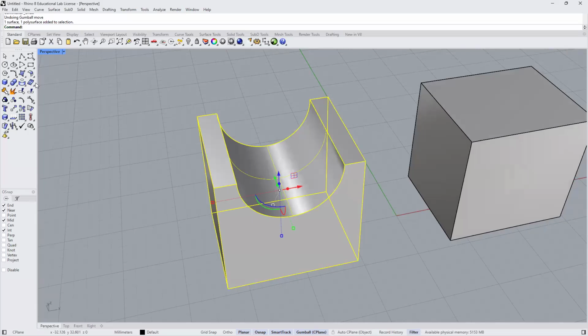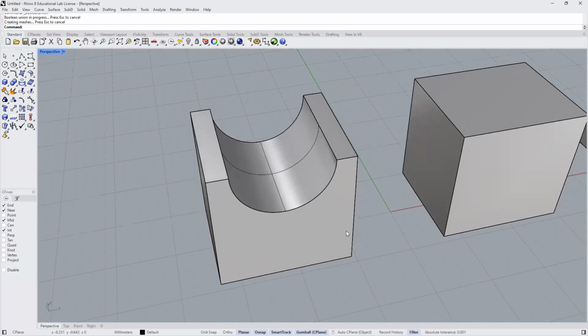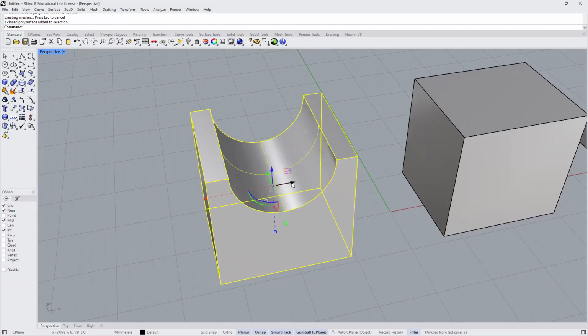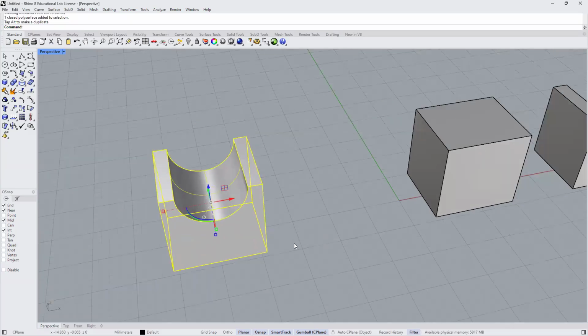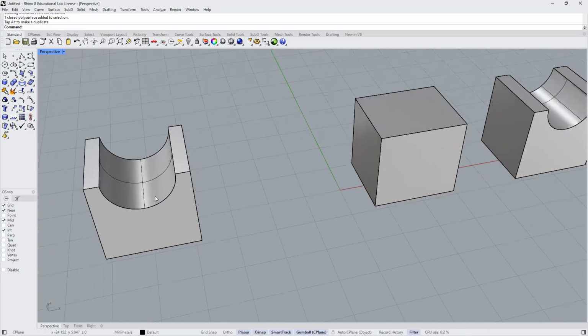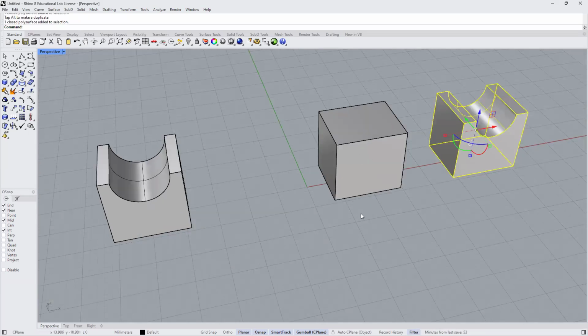And then I come back over here to my icon, and it currently is set to Boolean union. And if it was not, just cascade to that solids tool, and then you would select it, Boolean union. Click on it, and now what it's done is it has unioned all of the surfaces. To double check that, looks like it is done. But to double check, click on it and then just move it. And if it moves as one, then you know that you have unioned that. So I guess I did a Boolean union here, and over on the other side, I used the Boolean difference.